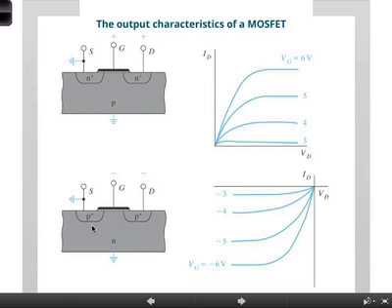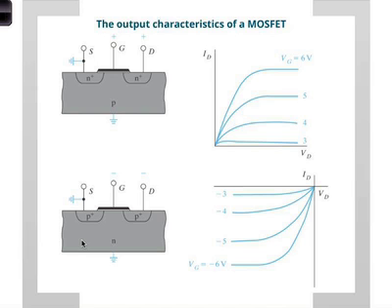Okay, now looking here, of course it can flow both ways, but now when I apply a drain to source voltage, where this is negative, that's positive, the polarity is flipped, the holes will flow from where to where? In this situation, look at this picture. Imagine a P-type channel right there exists because I've applied a negative voltage to the gate. Now let's say this is the situation. I have drain voltage applied like this. Is this grounded? It's negative. Which way will the holes flow? Yes, source to drain, right? Because that's a negative voltage. It will attract the holes.